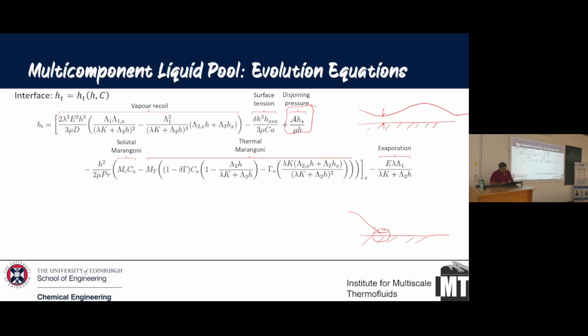We can say that the moment the height of the film becomes close to the Hamaker constant or becomes close to the disjoining pressure equation here, that is when you almost will have dry out. It's not fully dry out, because there is a film, but this is a device to control that. And as you would know, the Hamaker constant is completely dependent upon the van der Waals, and that is dependent upon the material properties and so on and so forth.